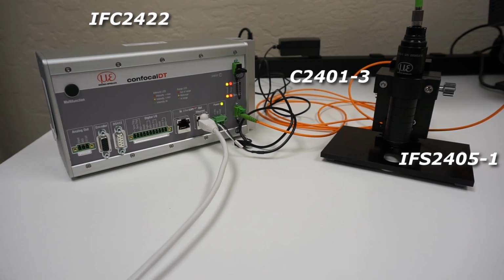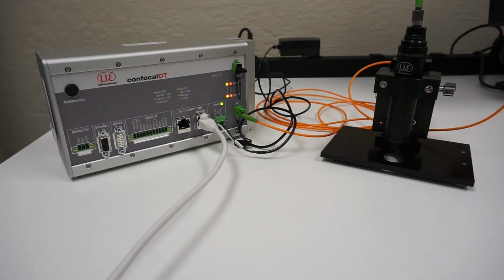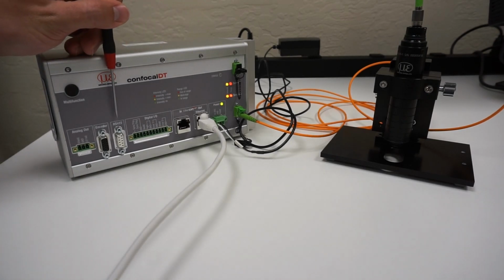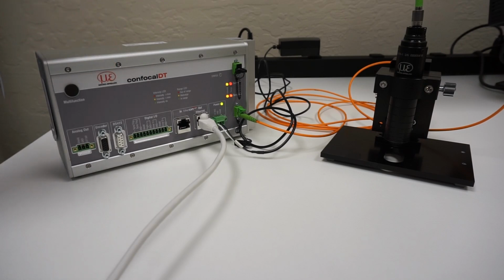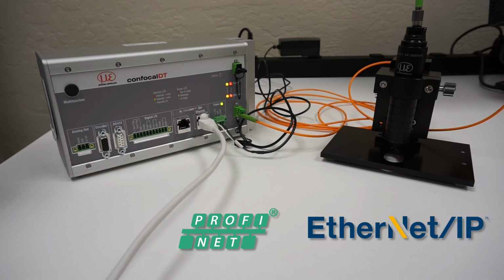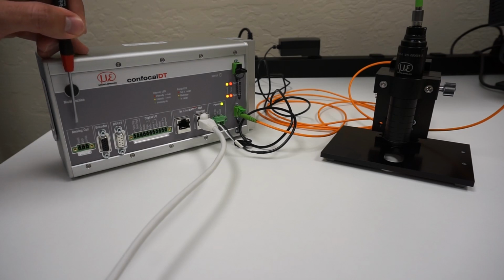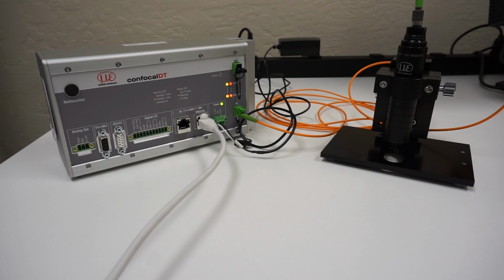But you have a lot of different integration possibilities. Aside from Ethernet, there are the digital interfaces EtherCAT and RS422. And with a separate interface, you could even integrate into Siemens PROFINET or Allen Bradley Ethernet IP. And just in case you'd rather like to evaluate analog signals, there is also 4 to 20 milliamps and 0 to 10 volts. That is the hardware part.